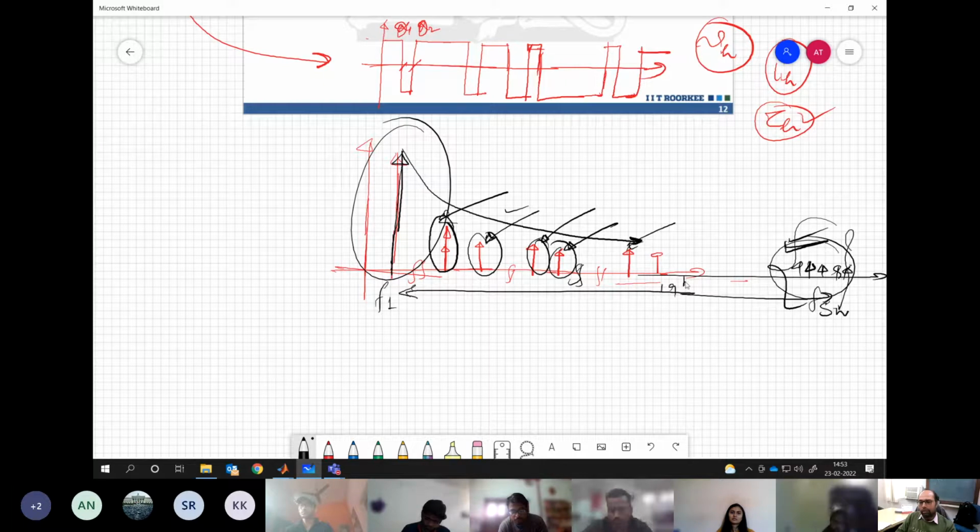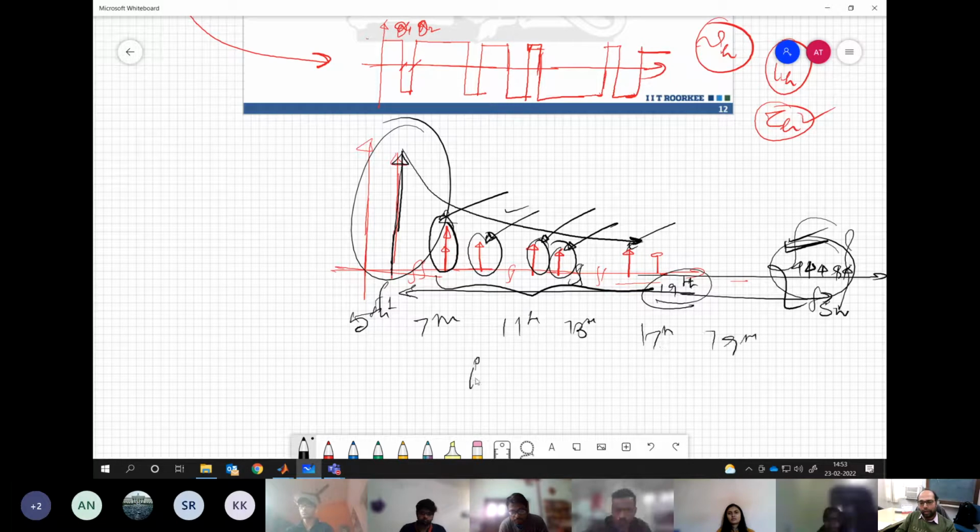Let's say up to the 19th, someone will say, okay, I will get the information about harmonics up to the 19th order, and then I will compute the cumulative effect of this. You understand my point? So we can do the analysis for 5th, 7th, 11th, 13th, 17th, 19th. We compute what are the harmonic currents, and then the corresponding torque. Torque will be the combination of these two, right? So all these things we can analyze harmonic order wise. That's what we have done for low switching frequency.